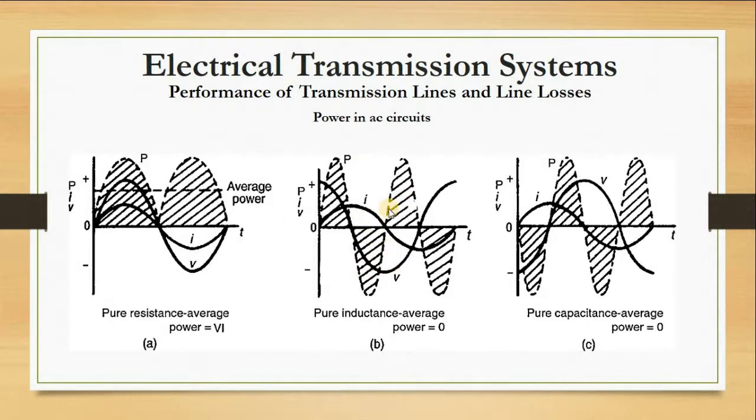Once you have a voltage source, and you also have an inductor, and there's a switch between, once you close the switch, if the supply of current to that load is, let's say, 2 amps, you are causing a change in current from 0 to about 2 amps through the inductor.